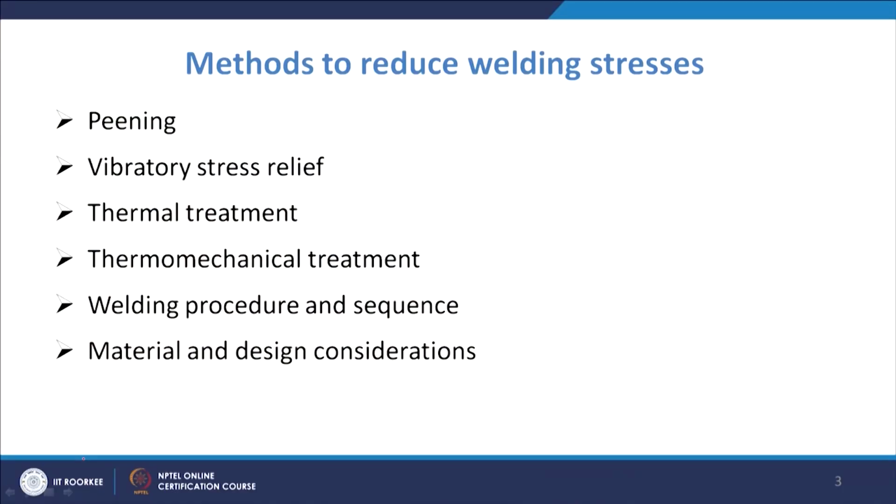The different methods which are used for the elimination of the stresses are peening, vibration stress relief, thermal treatment, thermomechanical treatment, welding procedure, and also material and design considerations.